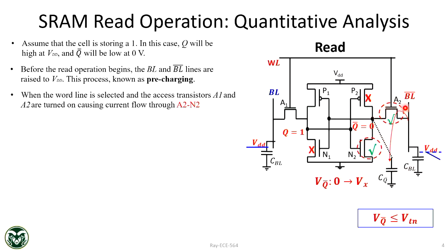Now, the moment this capacitor is beginning to charge, this voltage is rising. VQ bar is rising. It is no more 0. The moment VQ bar is rising, N2 will be conducting current. Now, will N2 conduct current in saturation regime or linear regime?